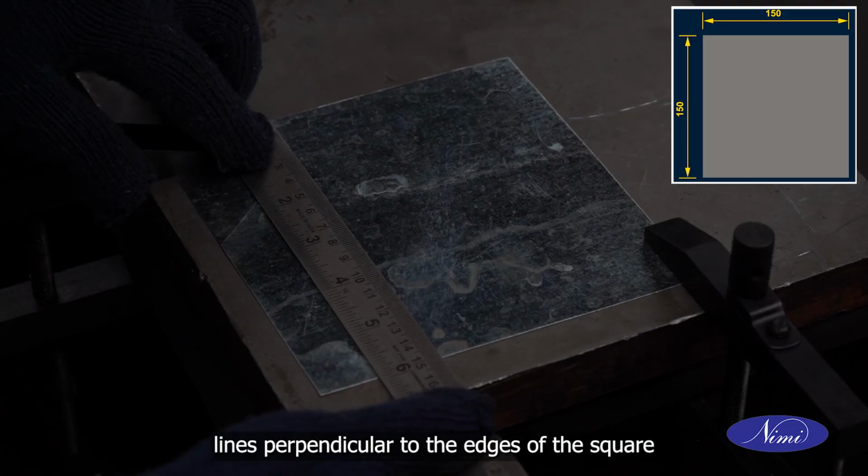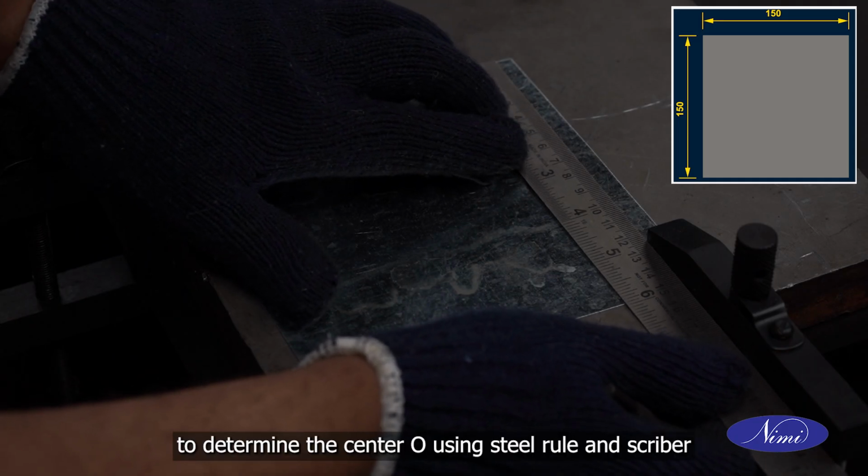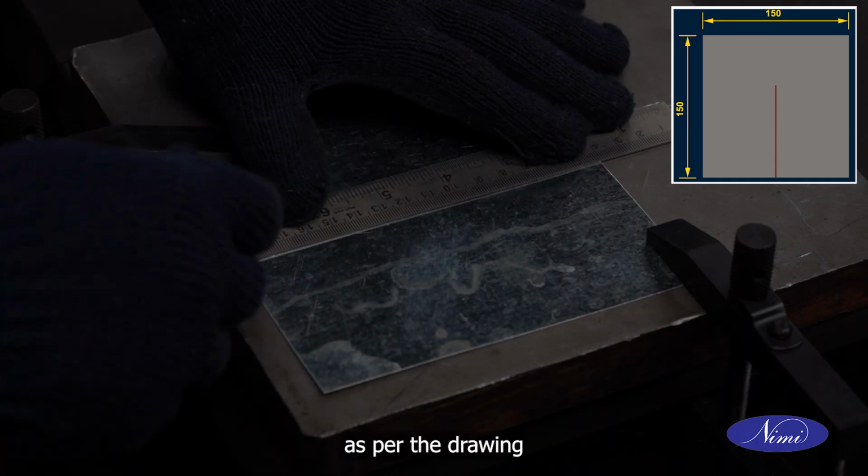Mark center lines perpendicular to the edges of the square to determine the center O using steel rule and scriber as per the drawing.